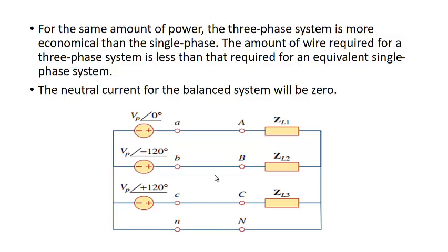In case of a single phase system, we have one live wire and one neutral wire. And in case of three-phase systems, if that was similar to that, then we should have three phase live wires and three neutral wires, and the size of the three neutral wires would have been more. So here, since the current flowing through this is zero, the requirement is only a single neutral wire, and we sometimes omit the requirement of the neutral wire.